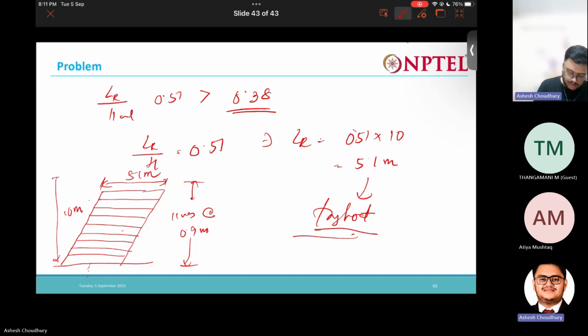And one more thing you can do: if we are using facing blocks, like in previous cases, to prevent eccentric loading, even small layers of this geogrid, say 1 meter in length, can be provided at the top edge, like this.